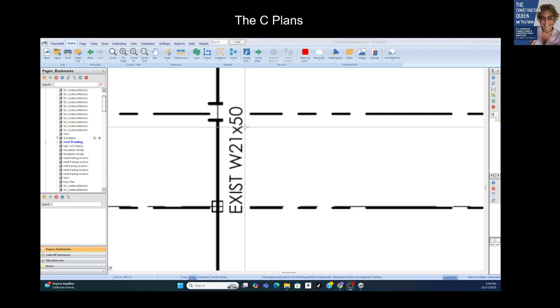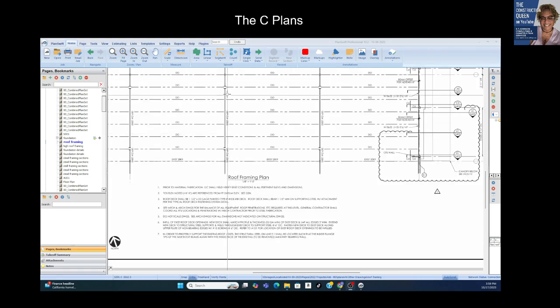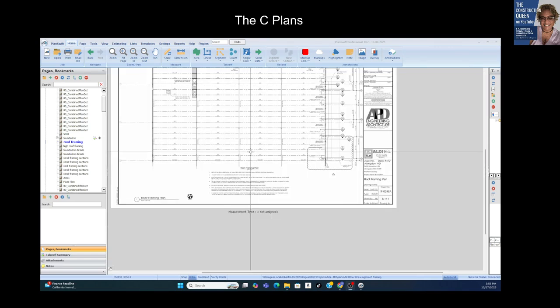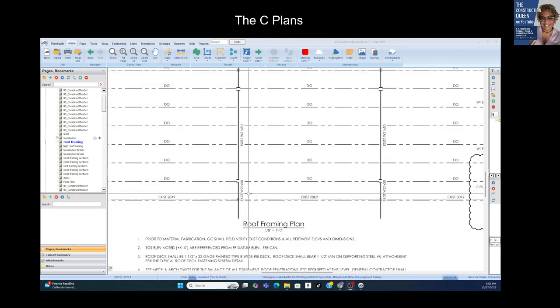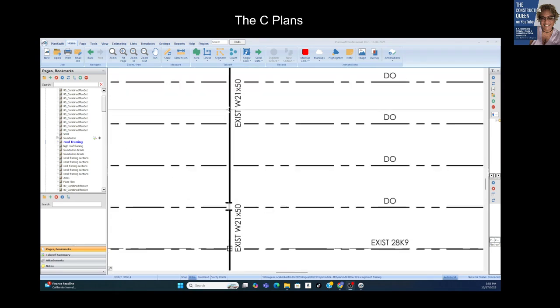And when you see the W beam, that's what those are, beams, right? And it could represent the beam or the column. In this case, it's going this way, right? It's up against this line. So you got to think structural framing. This is the framing plan, right? The plan is the view from above. It's as if we're in an airplane, there's no roof or anything. So we just see the rough framing. And so what we know from the plan is that these portions are W beams.